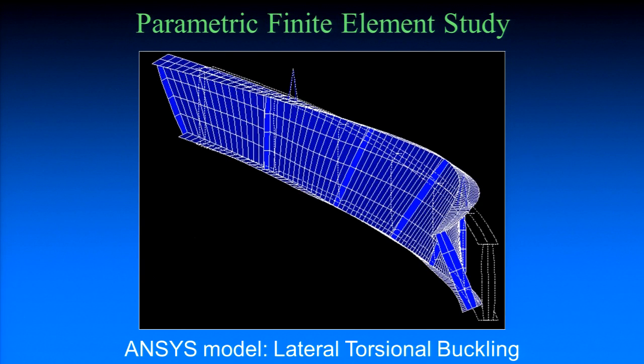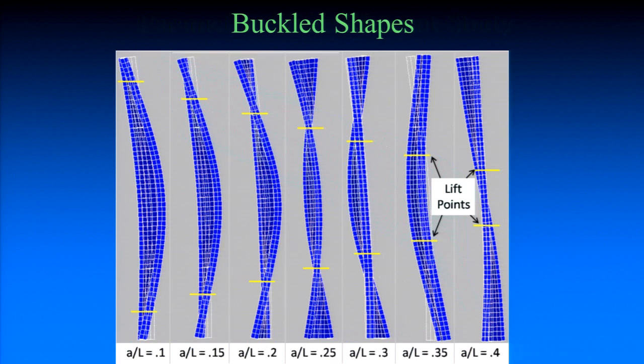This just kind of shows as we're picking this up, what the girders look like when they end up buckling. Okay. This just shows as we vary the lifting points how the buckling mode changes. So if we're out near the ends of the section like we would expect, it almost buckles like a simply supported section where the maximum deformations occur out near mid-span.